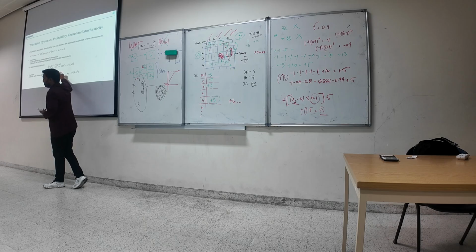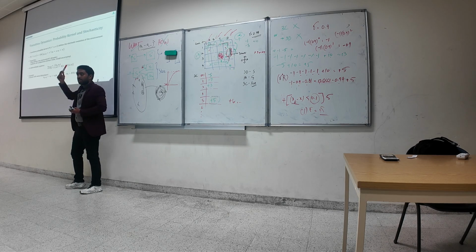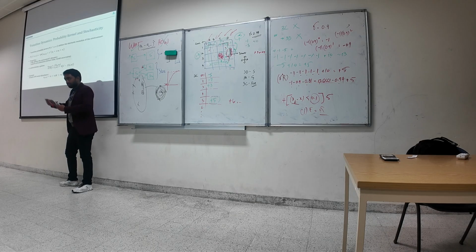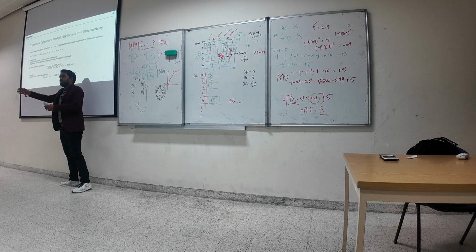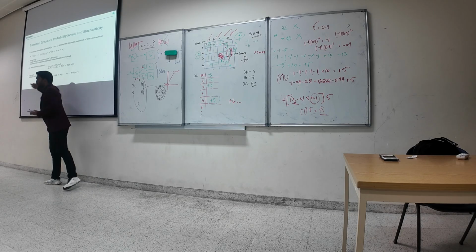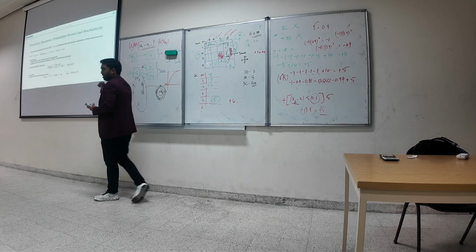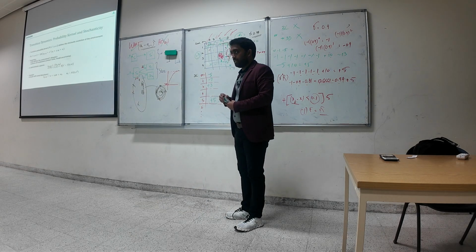Whereas say there is this wind disturbance, where the wind disturbance itself is a probability. Say this is a normal probability distribution with 0 mean and sigma squared as the variance. Then you have x_t plus v_t delta t, right? What does this mean? That the next position will be the current position plus the velocity times delta time plus whatever the wind disturbance effect is. Now this will give you a stochastic state. You're not 100% sure, because there is some kind of probability distribution involved. Clear on it? 100%?